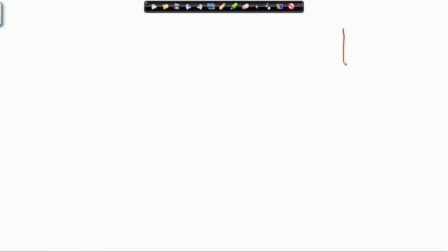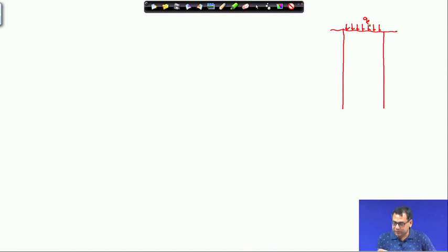First, I am considering the case where the stress on the conduit should be reduced. I will consider a narrow backfill, or a backfill which is loose, so it will deform. This is the yielding part, and this is the ground surface where we are applying a stress q.